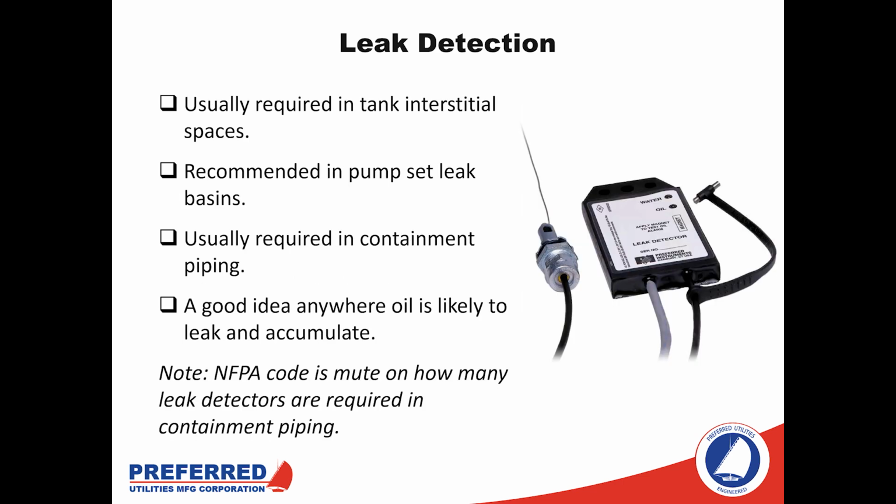Taking a look at leak detection, this is going to be present for the day tanks as well as the main tanks, and it's pretty much going to be required in any sort of double wall tank. There are multiple different kinds. We have many different systems out there, depending if we're talking containment piping or a tank or a sump. And we have leak detectors that can discriminate between the presence of oil or water or even vacuum-based systems. So there's a lot of different options out there, and depending on what kind of system you're using, there may be one that's best for that.